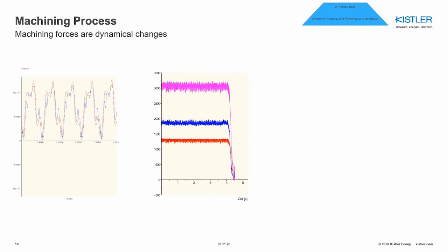If you look at turning, you have both the static part but also the dynamic part, the changes in your force fluctuations. So when you have built that base in the former slide, and then on top of that you have the online measurement, you will have more understanding and a much better chance to build monitoring and optimizing of your process.